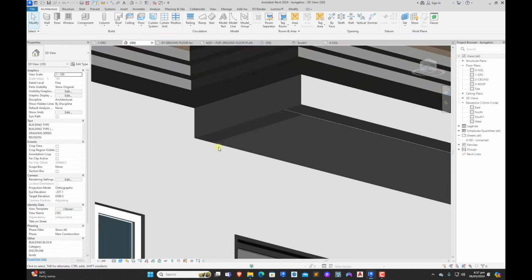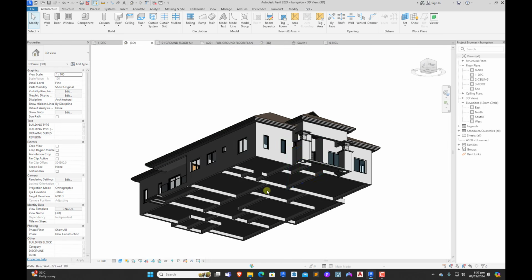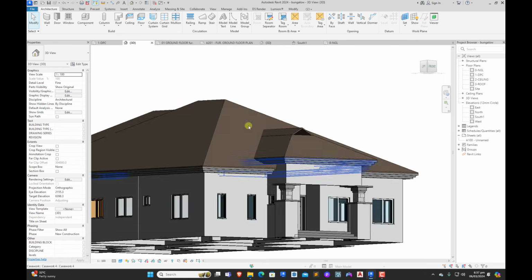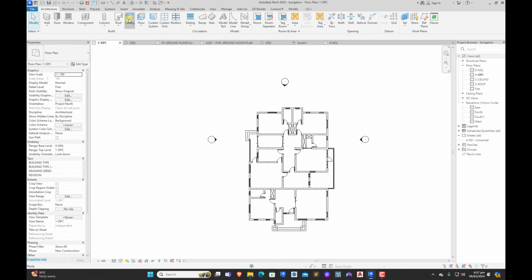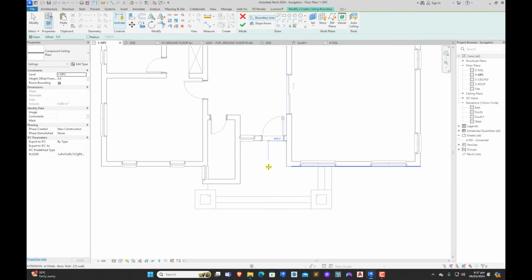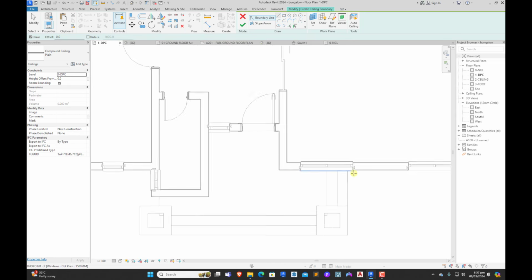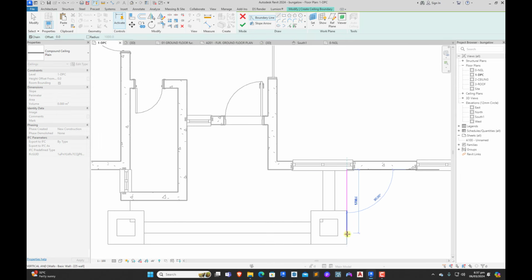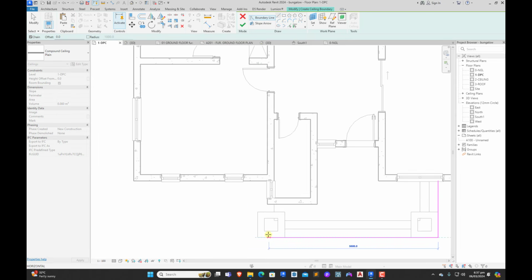Yes, this is nice. So now the next ceiling we're going to do is the one for the entrance, because it's a little bit lower. So that's a different ceiling. We're going to do it separately. So we click on our ceiling the same way, sketch ceiling, and we draw our ceiling this way. Now because the walls are higher than normal, we don't know where the walls are stopped at. So we're going to just sketch this first.